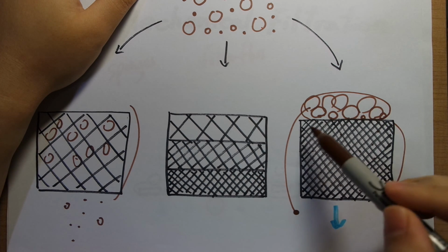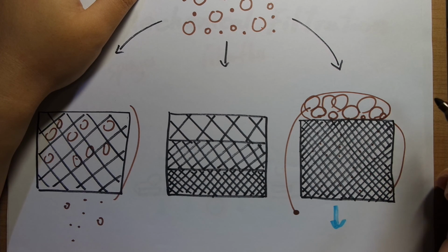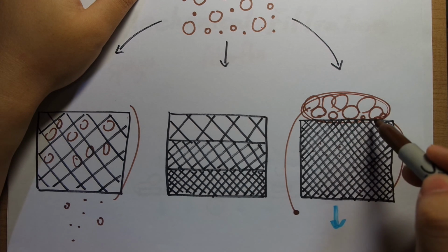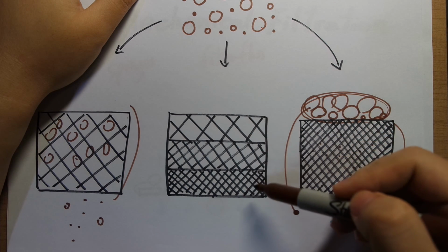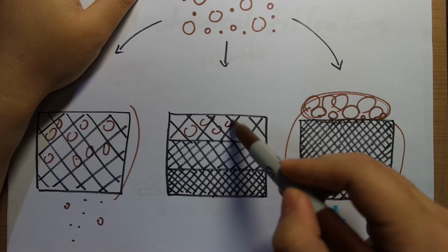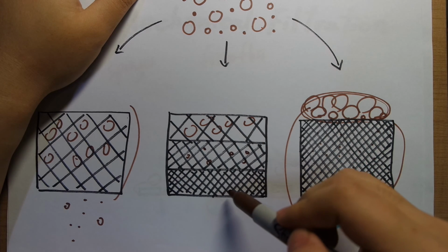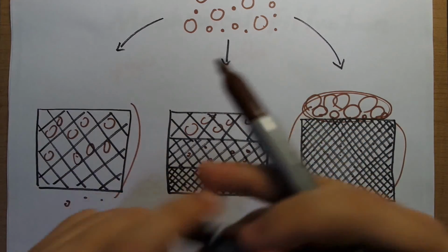So if you have a setup like this where you only have one kind of very fine mechanical filtration, that just means you'll need a filter that is maintained much more intensely. You would need to clean out this filter a lot more often to get rid of this gunk that is blocking your filter. The ideal way to do it is to have it in a variety of layers. So basically you start off with a coarse layer, so the big stuff gets stuck here, and then a medium layer where the medium particles get stuck, and then you end with a fine layer so it catches all the fine particles, and then you end up with clean water.